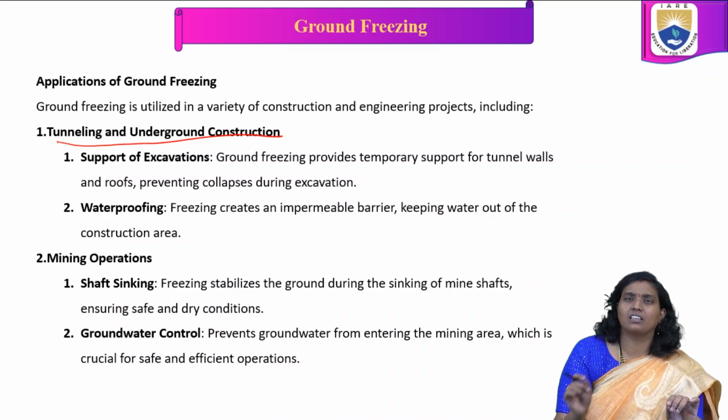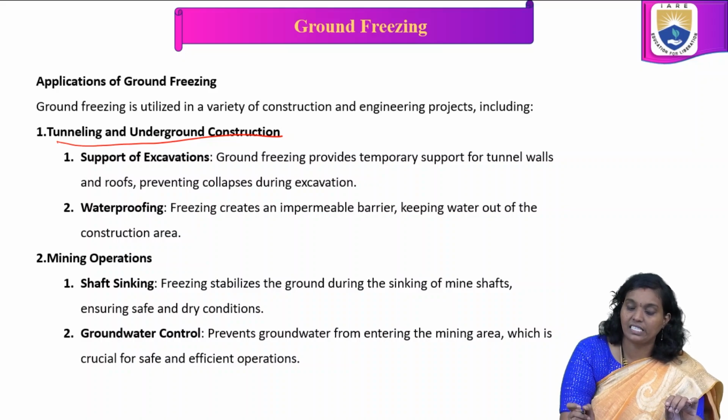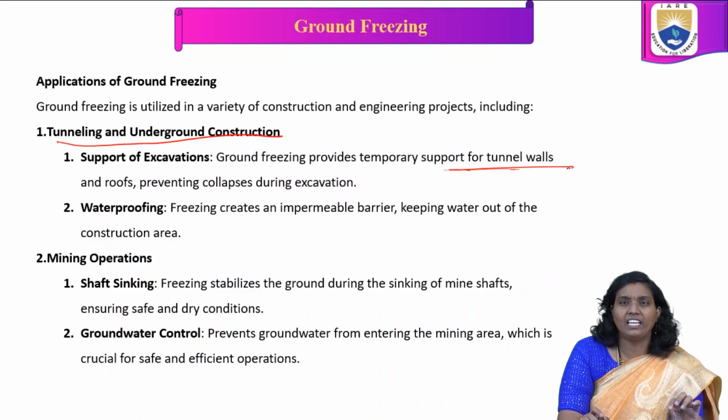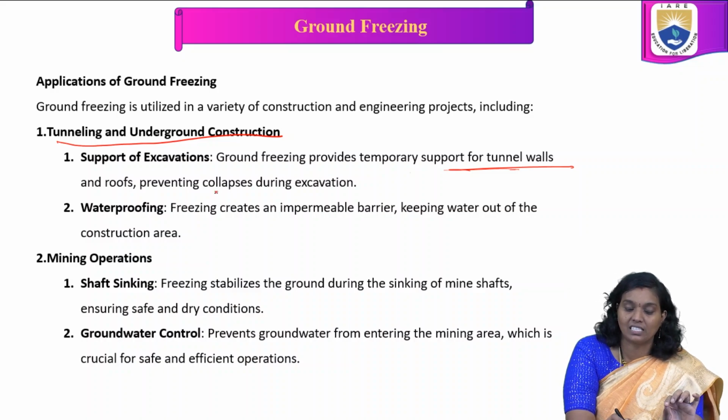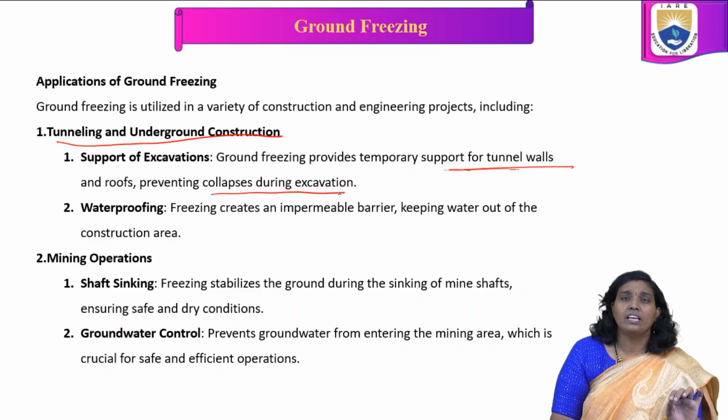Support of excavation: ground freezing provides temporary support for tunnel walls and roofs, preventing collapses during excavation. Waterproofing: freezing creates an impermeable barrier keeping water out of the construction area.